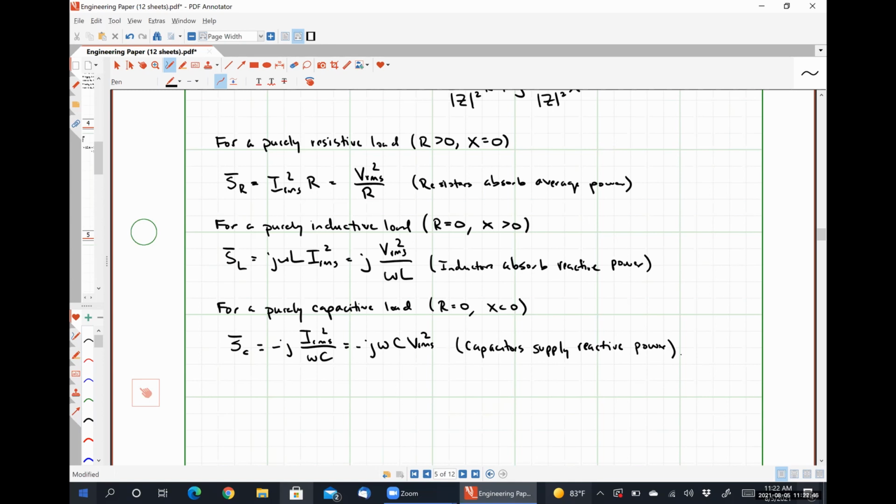Problem 1, you are given several time domain voltages, and you are asked to find the average power absorbed by the resistor. So what I would do for problem 1 is get those time domain voltages to effective voltages, and then use the effective voltage to determine your average power, because it'll just be VRMS squared over R. So those guys are pretty straightforward.